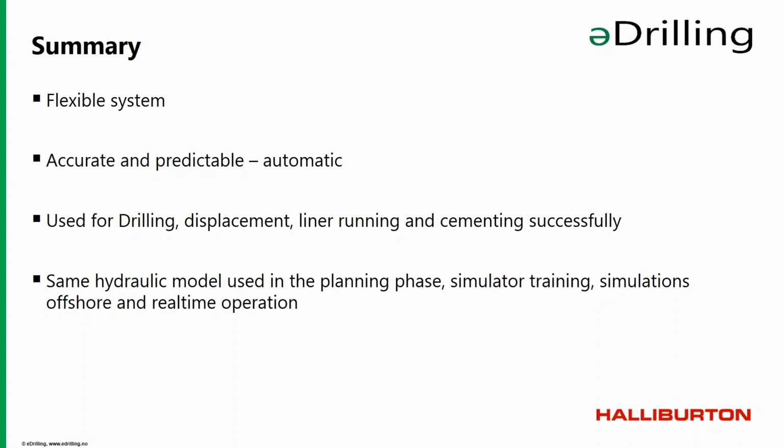Another question, can you elaborate on the differences going statically underbalanced versus overbalanced MPD? The difference is basically there are some wells where you have a very tight margin between the pore pressure and the fracture pressure, and you would see that if you chose a mud weight that would be statically overbalanced, then once you start your pumps you would have such a high ECD that you would frack the formation.